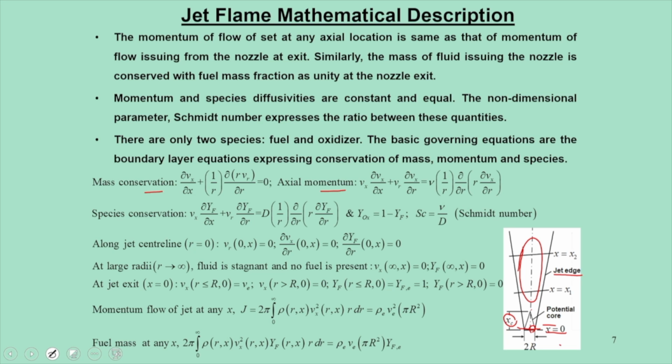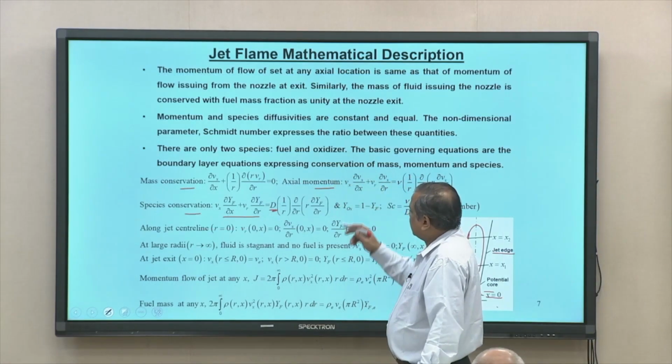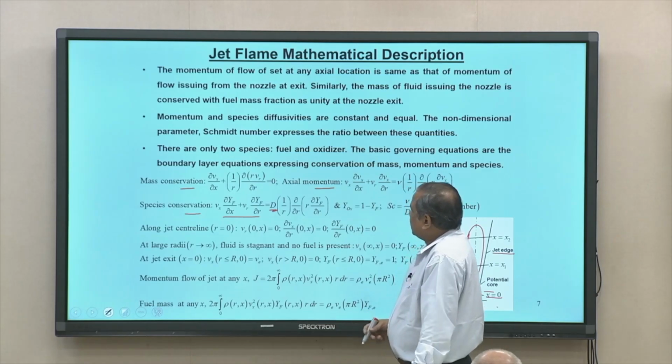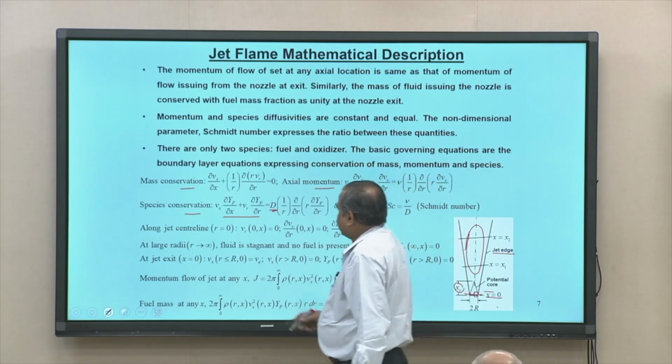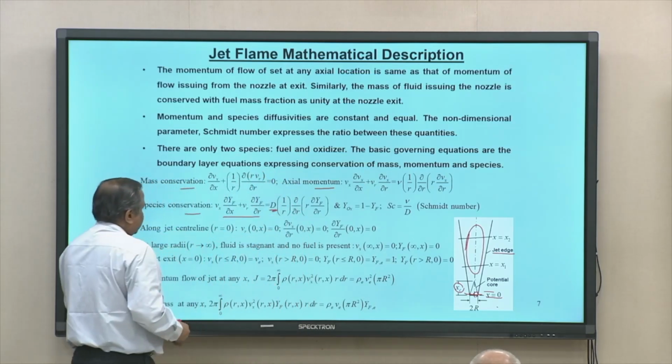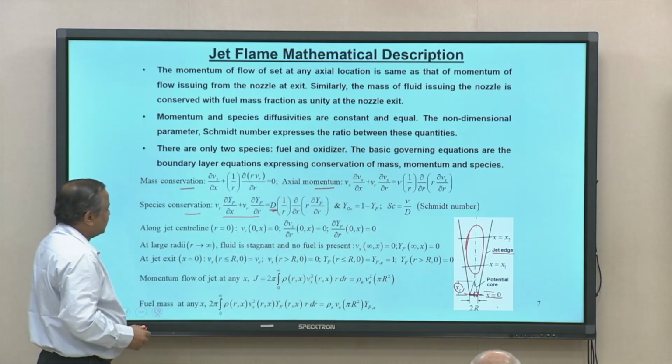Now in fluid mechanics terms, these two equations are sufficient to quantify velocity, but from a combustion viewpoint, since you are looking at fuel species, you have to find the species conservation equation in terms of its mass fraction. Here there is a term called d, which is known as the diffusion coefficient, and we can find this d through Fick's law. These are the governing equations, and we are trying to solve them with certain boundary conditions.